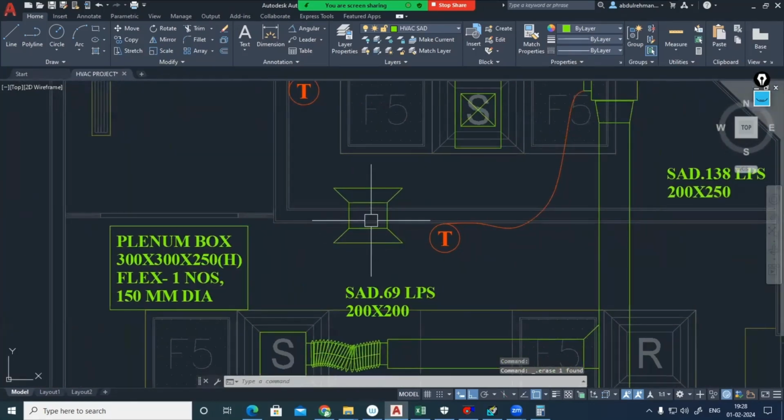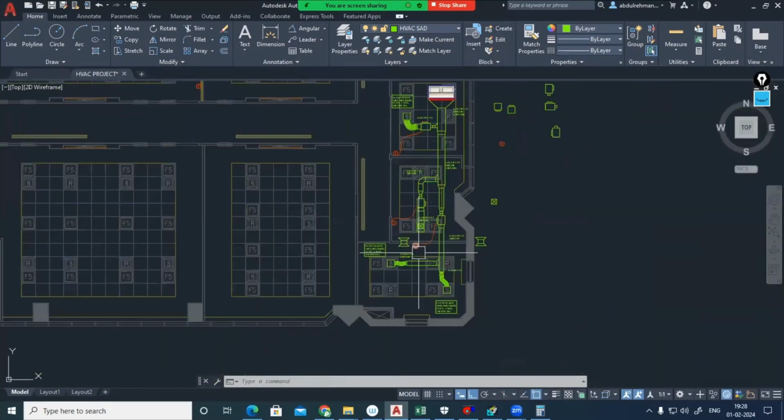And if you are planning to propose the fire damper within this duct, we can propose it. That will be acting as a duct for the return path, transfer air duct. But I'm not having any intentions to provide a fire damper there. So transfer air duct, additional cost will come, metal duct, no. So it is not mandatory. Avoid it. I just need a wall opening there.